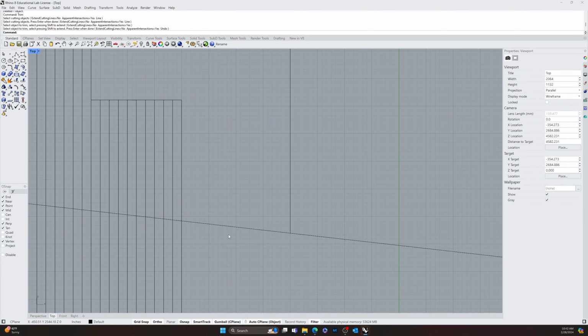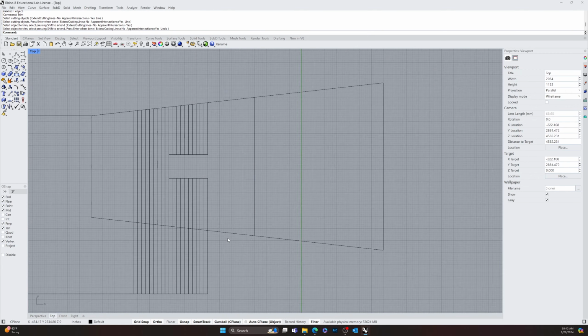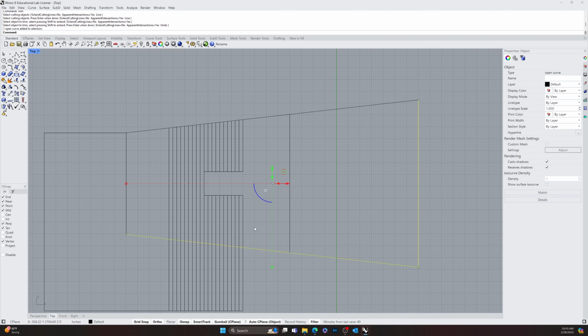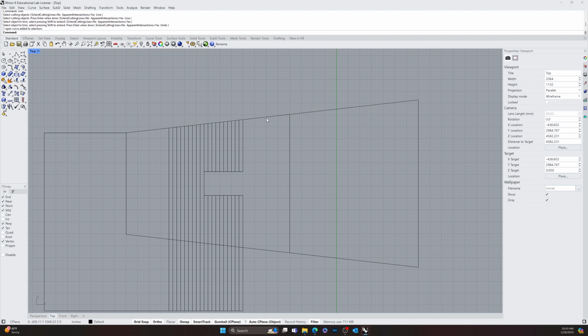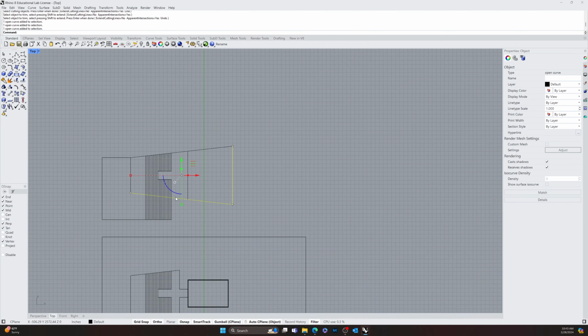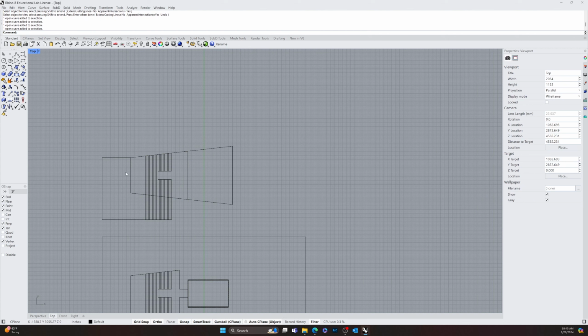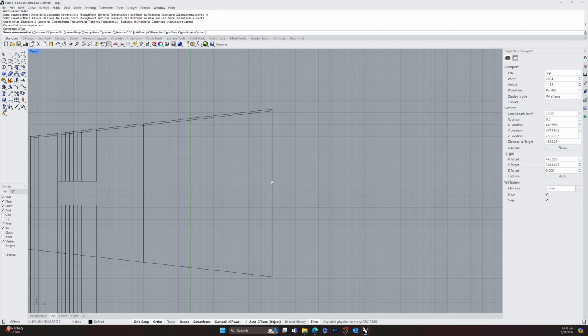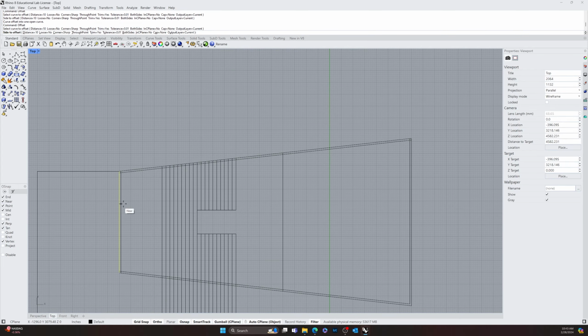Okay, and the upper floor of this building is going to have an area that you can walk all the way around. So I'm going to offset this in 10 feet. Actually, let's create the walls on the inside, because this is going to be the exterior walls. So let's offset these in, and then create our little mezzanine. So offset 10 for 10 inches. Click on this to there, enter, click here to there, enter, and then this to there.